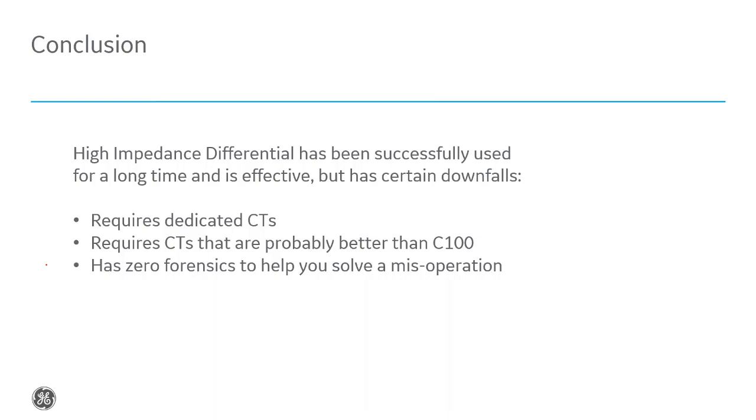Terry, I actually had a case where a customer was rocking and rolling along with a high impedance bus differential at a paper mill. One day they had a fault that was actually external to the bus, and sure enough, it tripped the bus relay.